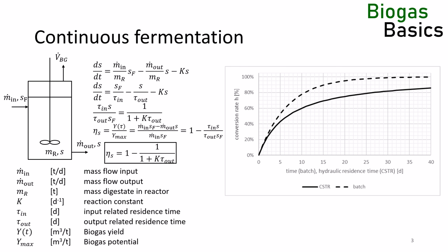The correct approach to determine the residence time of a CSTR to reach the required conversion factor is to quantify the degradation kinetics in a batch experiment with a mechanistic model, and then use the model to predict the behavior in a CSTR, projecting the desired conversion rate in a batch onto the time axis, and make that time the hydraulic residence time in the CSTR. This is really important. I have seen investors lose millions of pounds over this mistake.